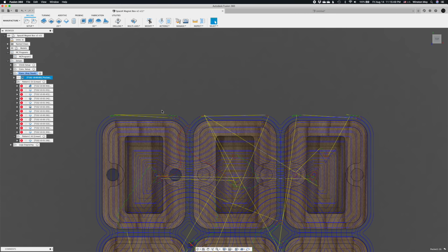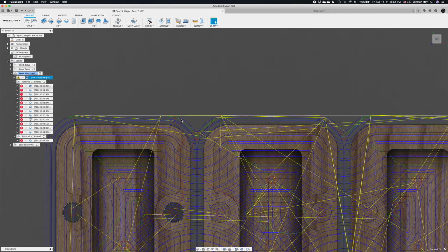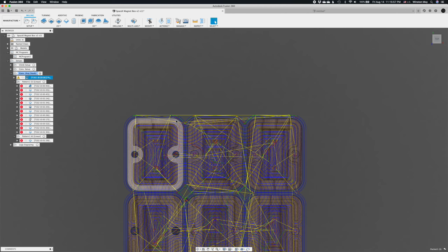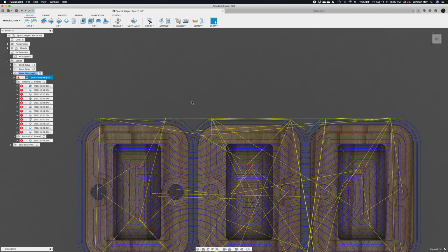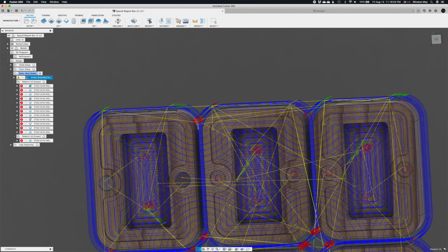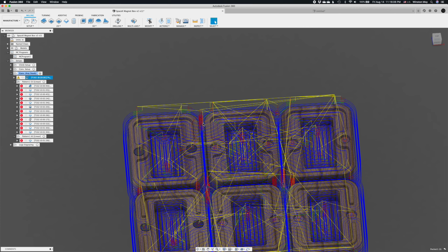If you have a table saw, you can totally just cut down pieces to the exact size you need, use a touch probe to find your origin at a corner, and have a slightly more efficient toolpath because the end mill can sort of dart in and cut what it needs to and then exit without helixing down everywhere.